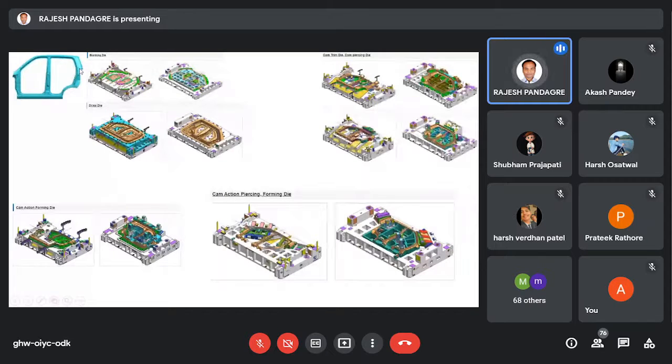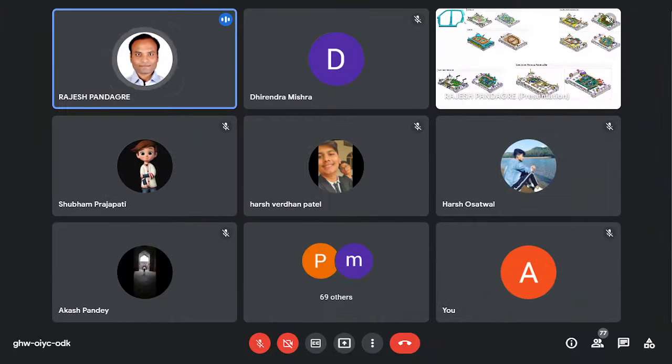What I mean to say is no cracks, no wrinkles, no kind of dimples or dash on this Class A. Whatever operation is being done is on Class B only, which is not at all visible on first look. So whatever analysis we do on the draw die, I'm going a little bit deep dive, so please be attentive.